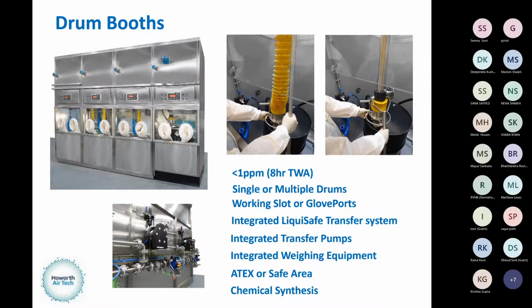It takes away the elements of handling a contaminated lance or a contaminated hose within that system, and then we utilize pump technology to transfer from the drum into the next part of the process, which, most of the time, is a process vessel or reactor system. So again, it's just taking that envelope and designing that around the drum transfer system.